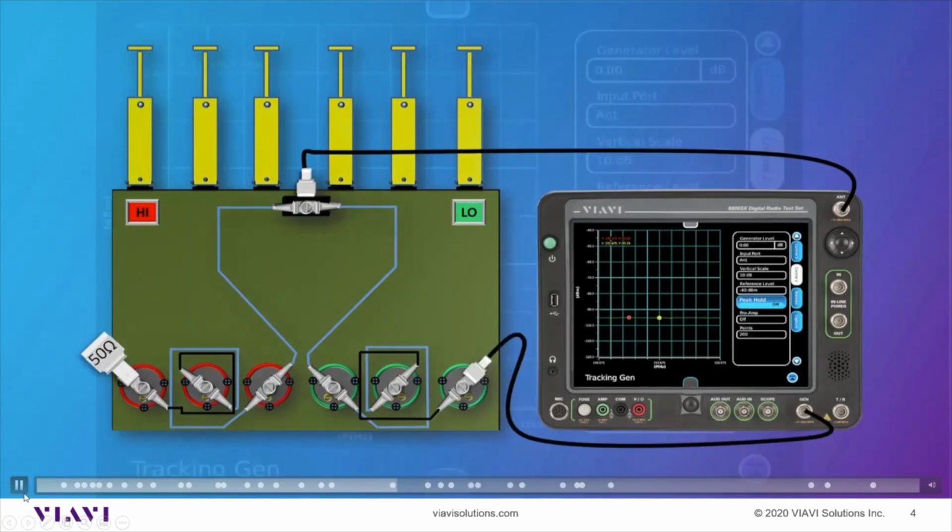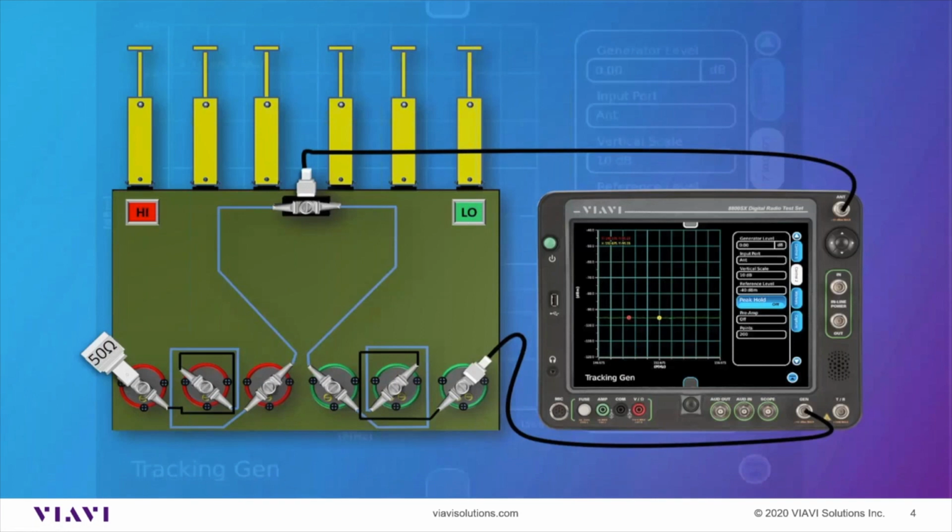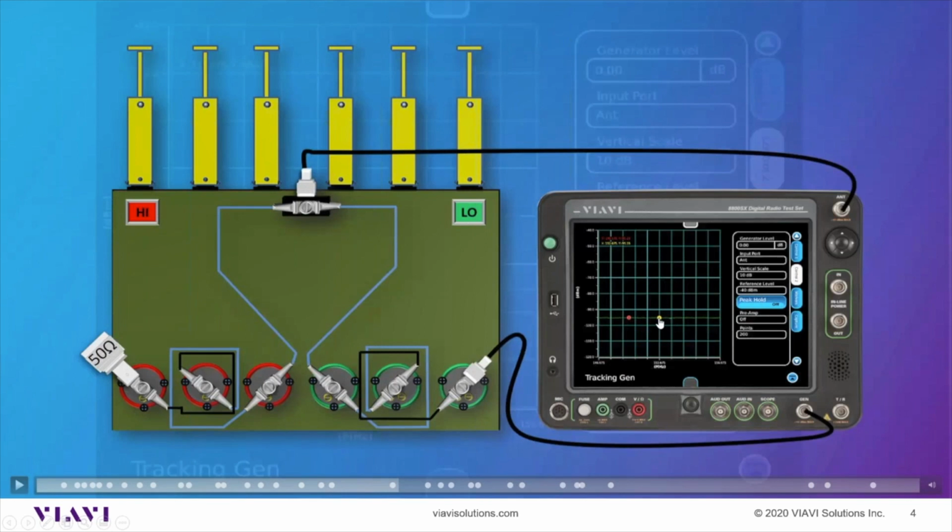Oh, and by the way, if I could hit it quick enough, what you're seeing right here, the cables at this point are actually not on here. This is the noise floor of the analyzer. And when we get a little bit further into this, after we put the return loss bridge on there, I want to take a closer look at those, because they explain a little bit about the noise floor versus the bottom of the notch, which sometimes can be a little bit deceiving.